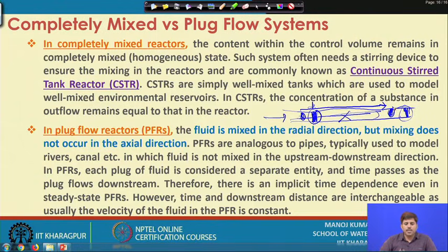So, in a PFR each plug of fluid is considered as a separate entity. Each plug is a separate entity, and as this plug travels within that space, time passes. So, there is an implicit time dependence assumption.